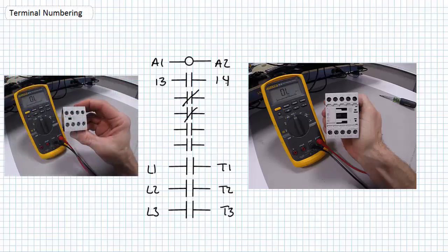If the application necessitates additional functionality, an auxiliary contact block can be utilized that includes other auxiliary pilot level contacts. When the coil is energized by pilot voltage, these auxiliary contacts would also change to their opposite state. Note that the first digit in the terminal numbers for a contactor's pilot contacts identifies a particular switch, and the second digit pairing indicates that particular switch's deactivated state.